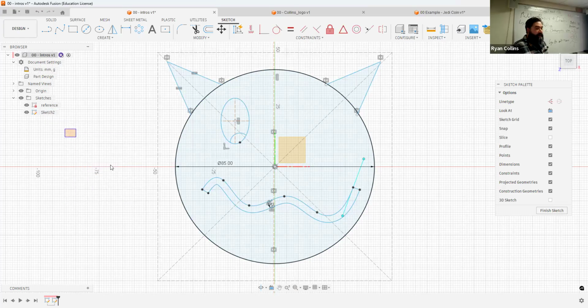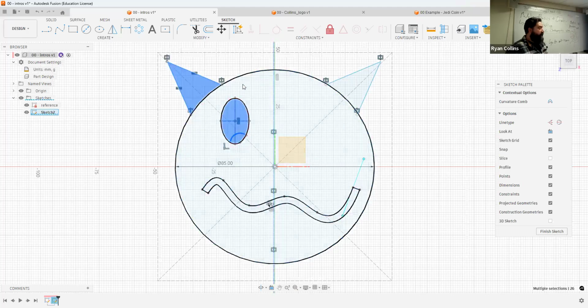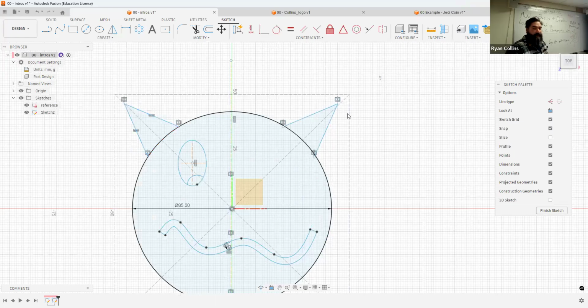But that's if I click from the left and drag right. If I click from the right and drag left, you see how it's now a yellow box with dotted lines. The difference there is from the left and dragging right, we'll select only what is completely inside of that box. See, it ignored the outer line or anything like that. If I select from the right and move left, it will select everything that box touches.